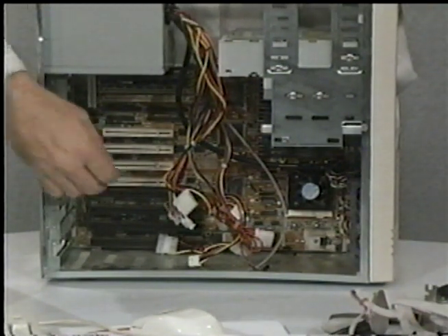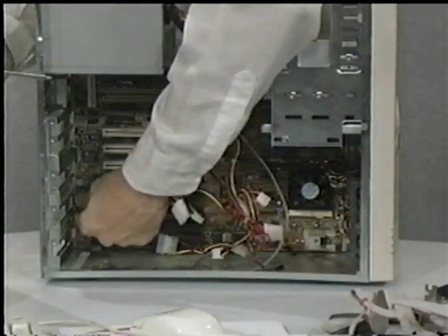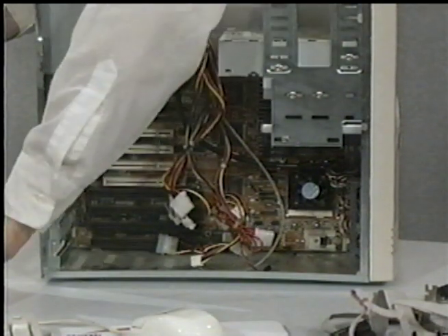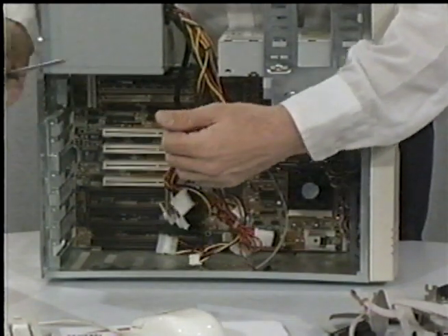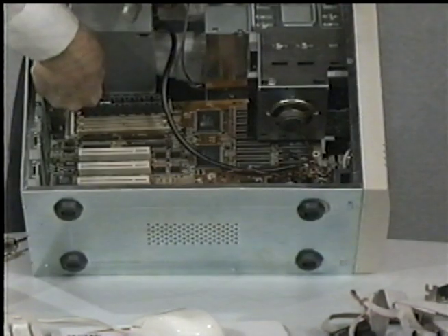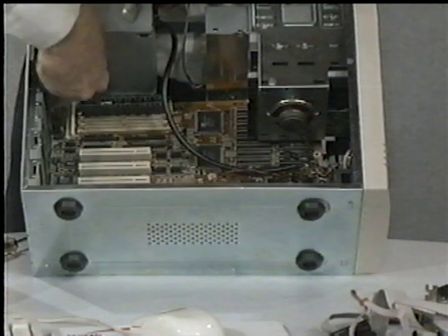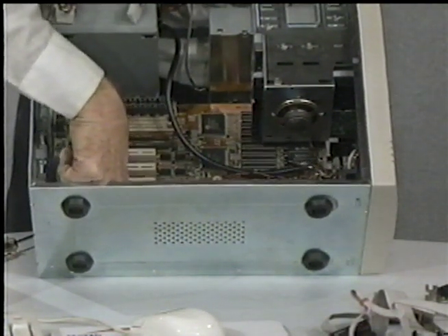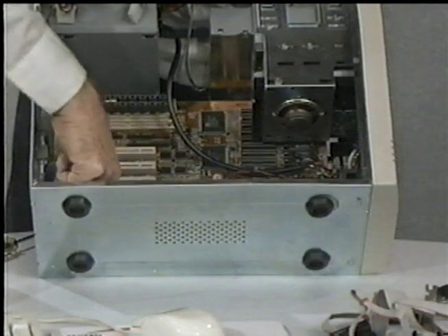With all the cables except for the chassis display cables removed from the motherboard, we'll now remove it from the chassis. We simply remove the screws that attach the motherboard chassis to the system chassis. Our motherboard has plastic clips that can be squeezed with pliers while applying light pressure from the back.